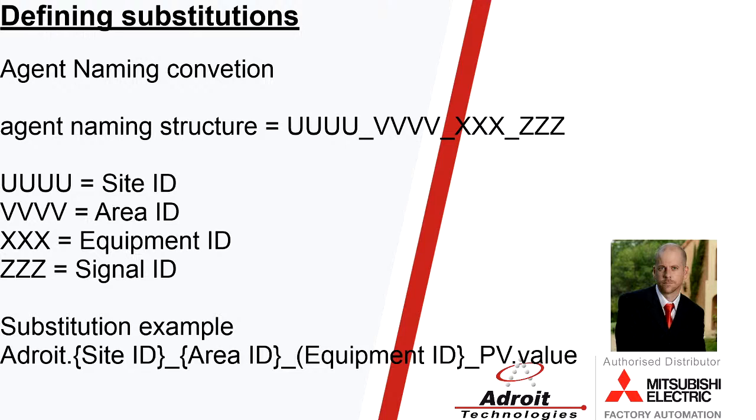The first part will be the site ID, as you saw in the previous example, that would be JUP. The area ID, which would be batching, in this case would be BAT. The equipment ID, which is feeder A, that would be FD. And then the final value would be a signal ID, which would be PV. So I've now defined my structure.